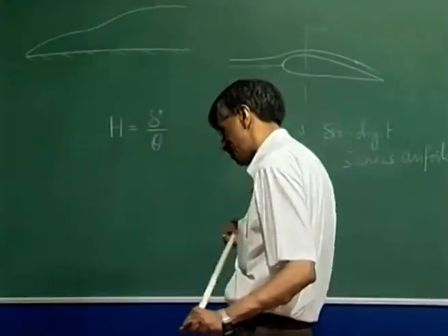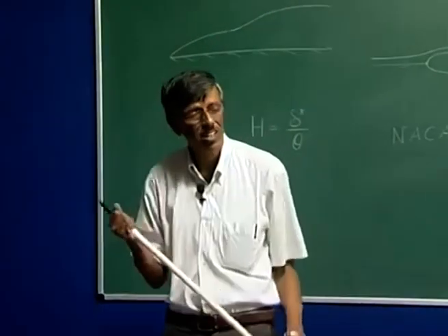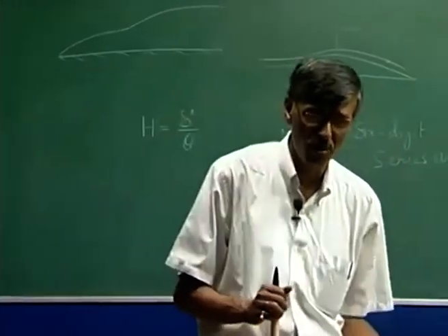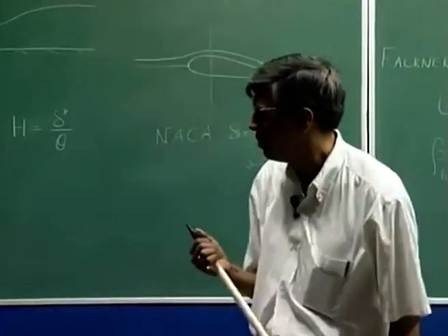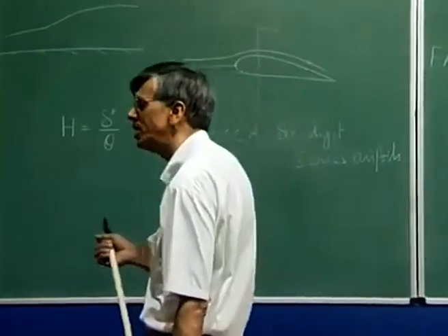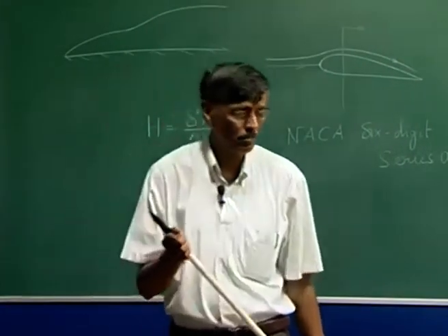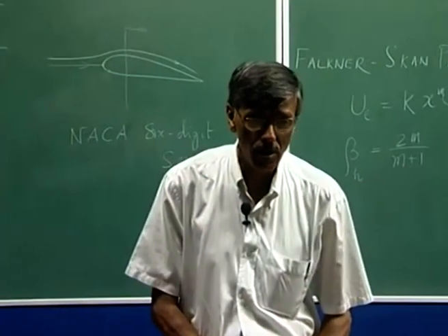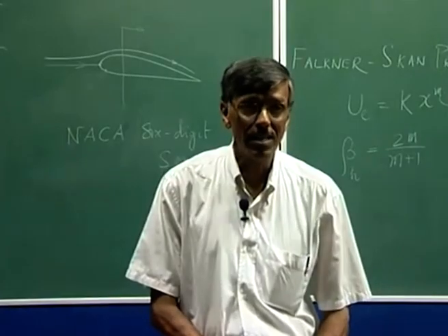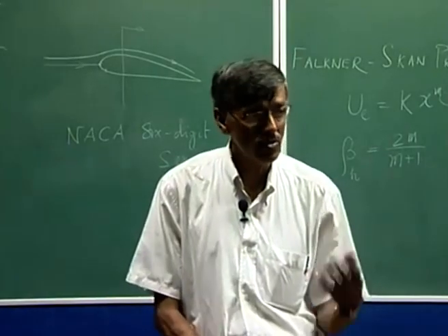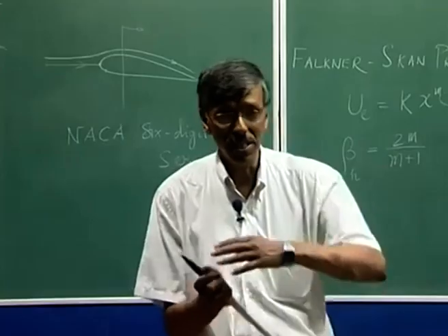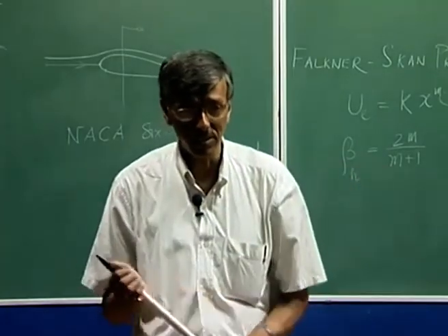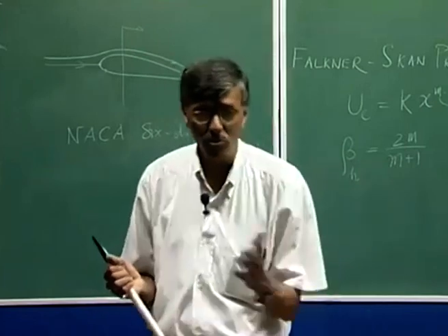Although people have talked about transient growth through the mathematical subtleties of non-normal modes, in some of our work we did show that even in a stable boundary layer, there is a possibility at the onset of disturbance you could get a very large spatiotemporally growing wave front.